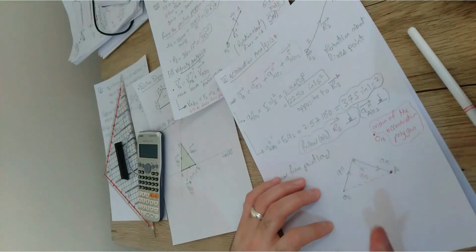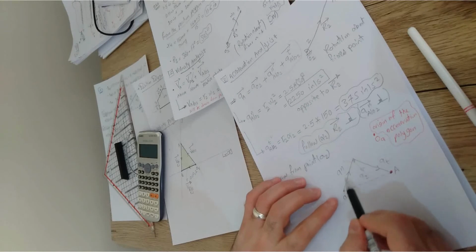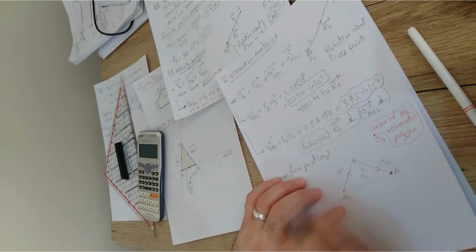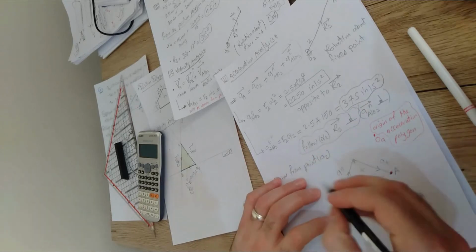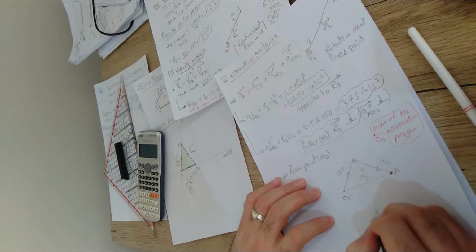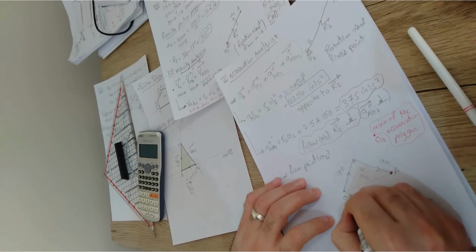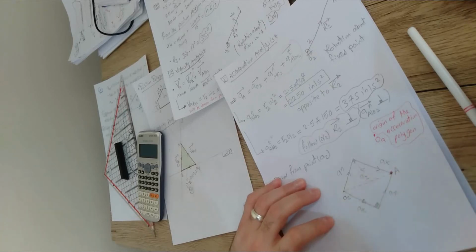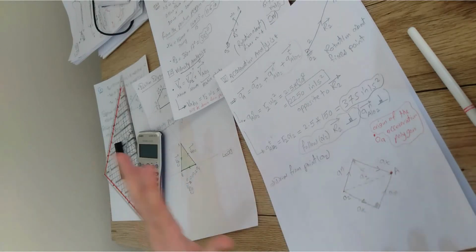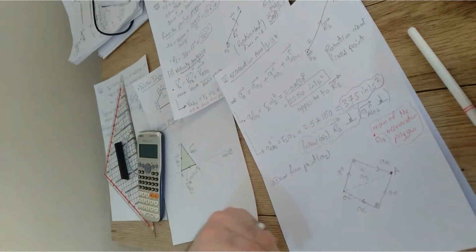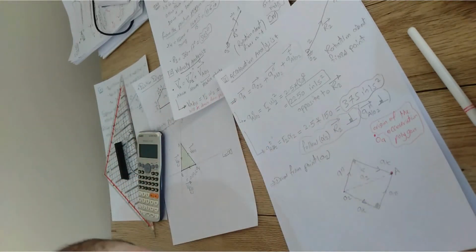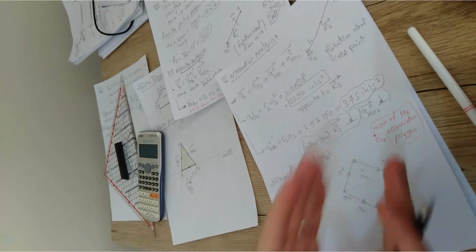Make sense? The other option here: I started by drawing the A normal, then after the A normal I draw the A tangential, but you can start with drawing the A tangential first. For example, I can draw the A tangential in this way, then take the A normal, drawn after the A tangential to be normal to the A tangential itself. Make sense? So generally, for a link that rotates about a fixed point, the normal and the tangential components should be perpendicular to each other. You can start with either the normal component then the tangential, or the tangential then the normal, it's up to you.